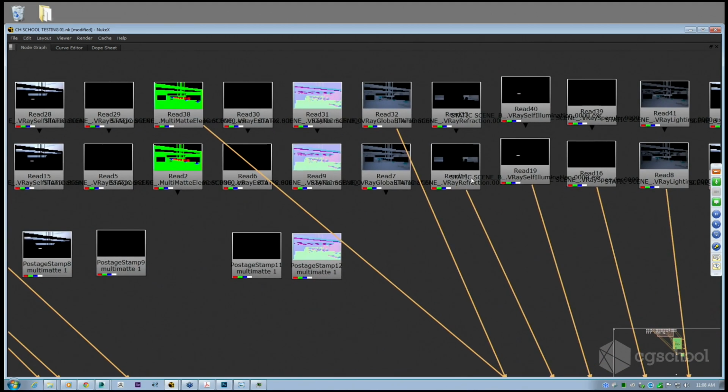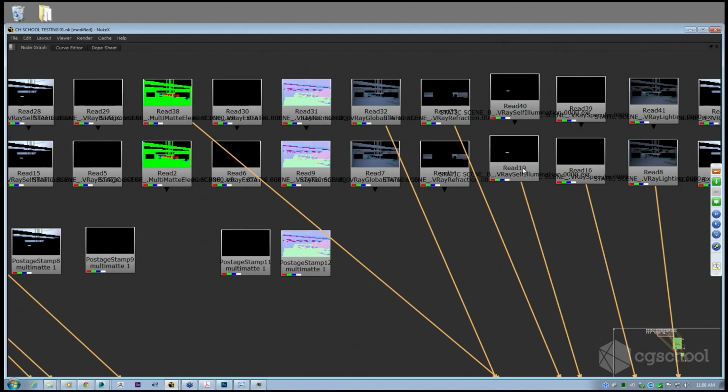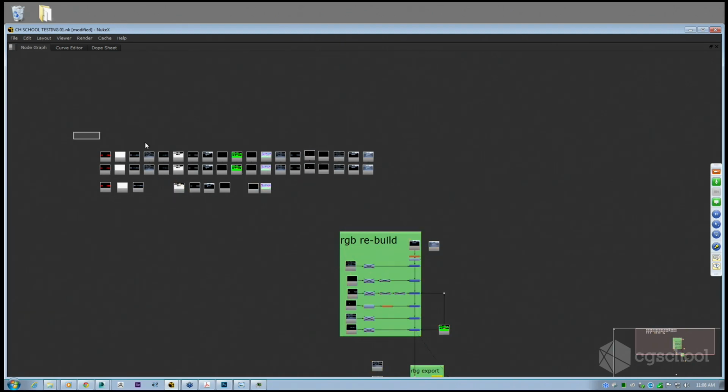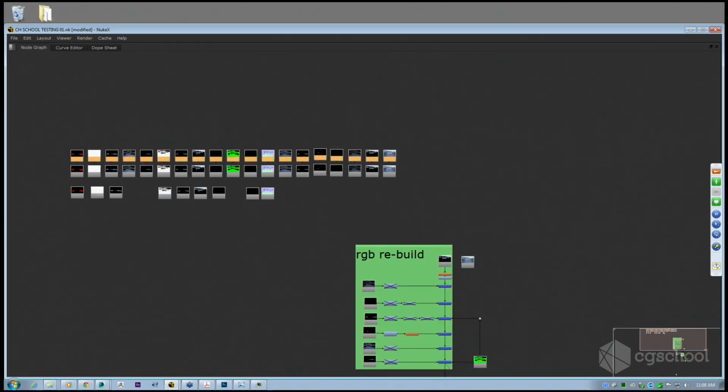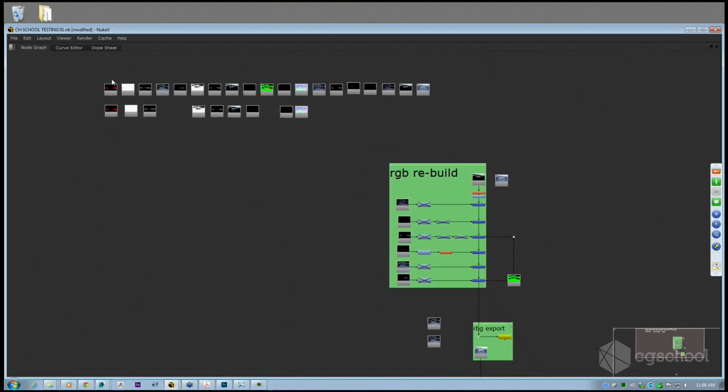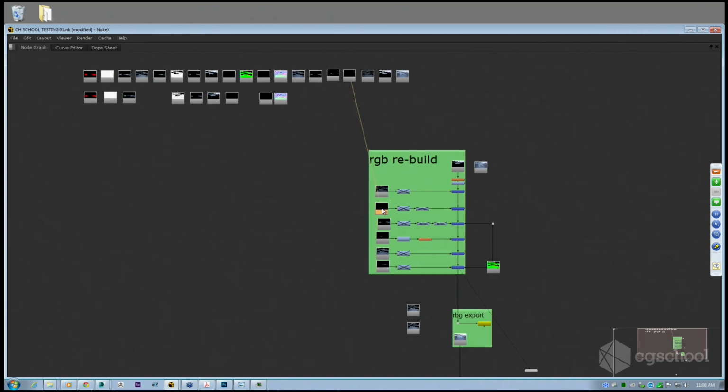What we tend to do, which I'll explain more later on, especially for our ArcViz image workflow, is that when we're in the development of a project, we have a working folder, a current folder, and then we save all of our latest renders into that, and we overwrite. But then we copy that current folder and we date it when we do that. So we've always got a record of what we've done. But then we can have a current folder which is always linked in our Nuke comp, and which is automatically updating every time we re-render. And then we have a comp which is automatically updating with all of our passes and things like that. And we'll go through that example slightly later on.